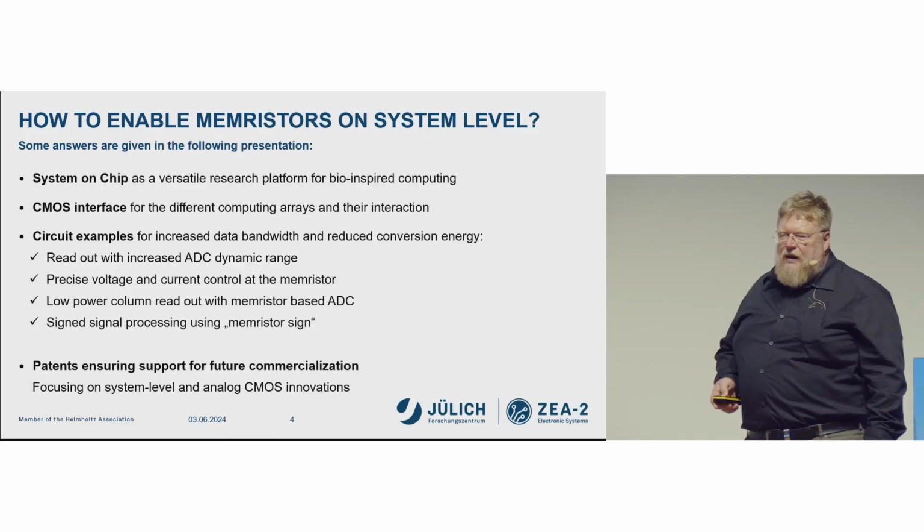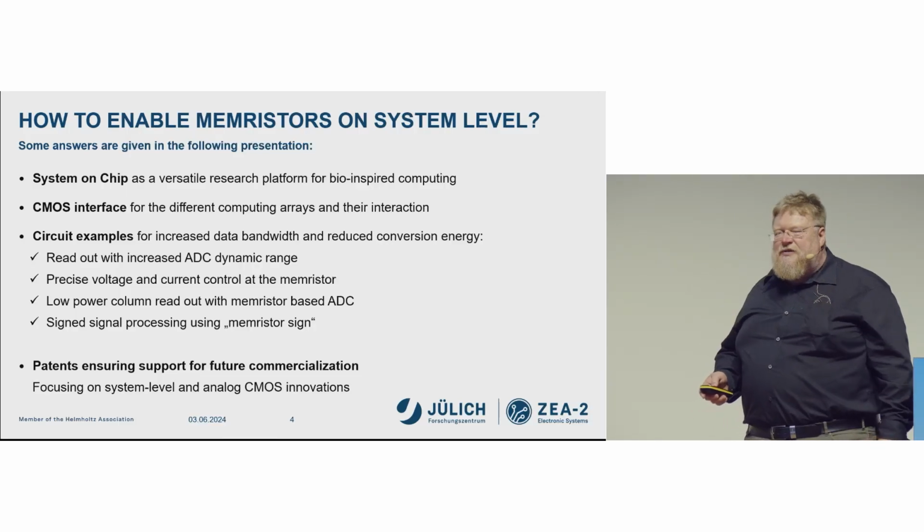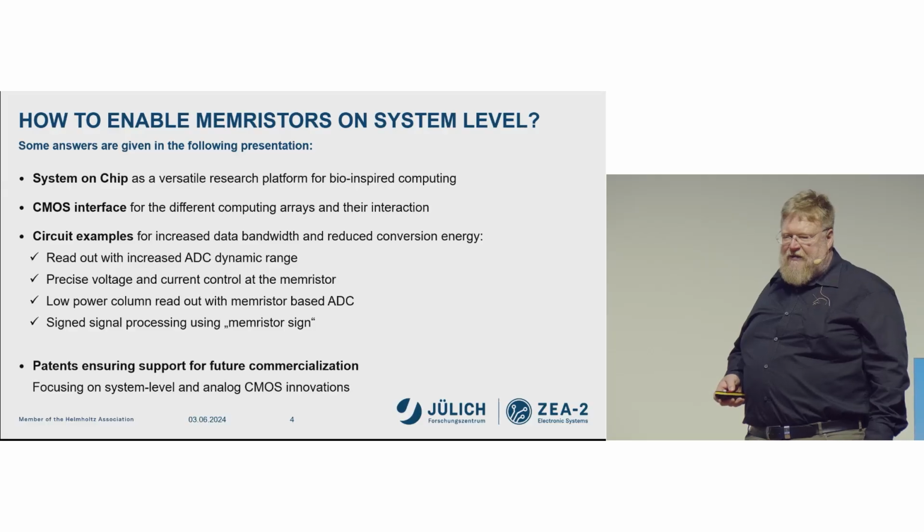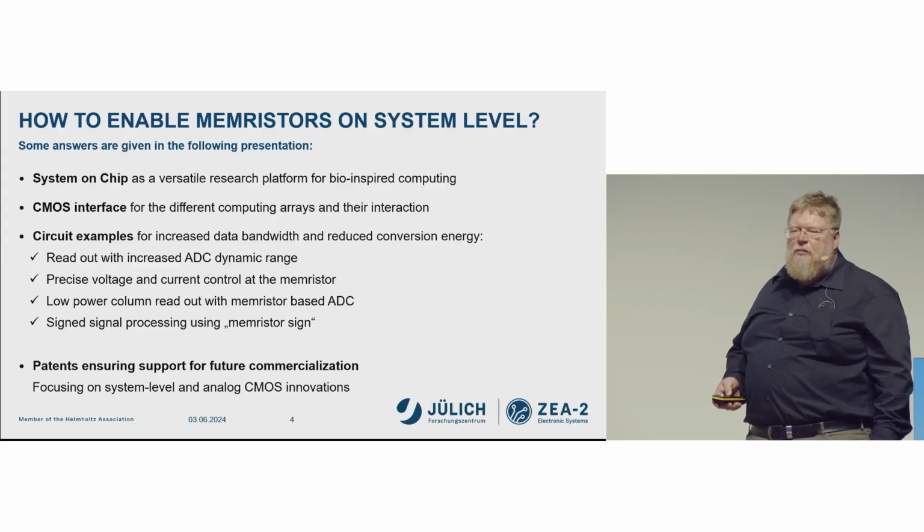So let's come back to the first question: how to enable memristors on a system level. In this talk, I will try to give some of the answers. There is a system on chip introduced in Neurotech 2, the demonstrator chip, which is thought of as a versatile research platform for bio-inspired computing. The CMOS interface on this chip, interfacing all the crossbar arrays, has different computing arrays, and the interaction has to fulfill different roles, which I will briefly talk about.